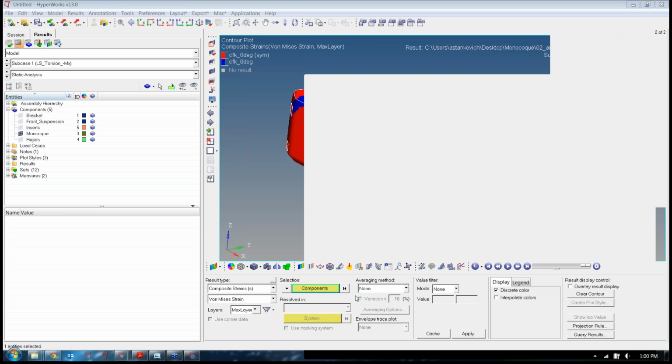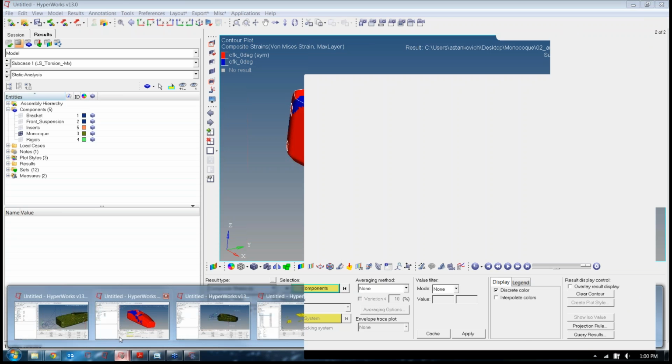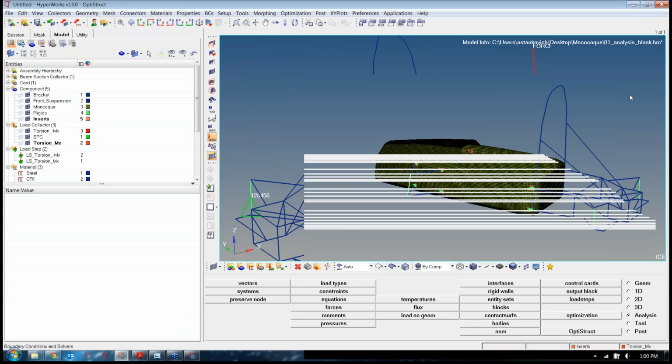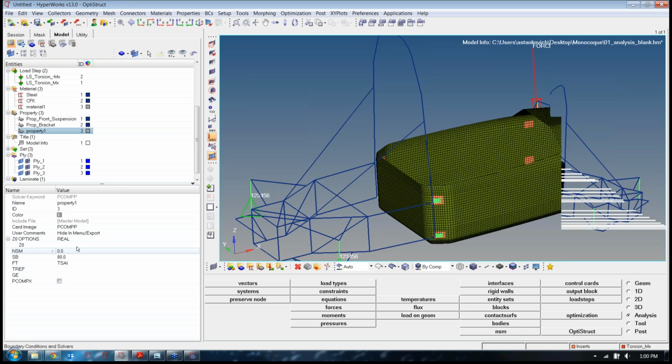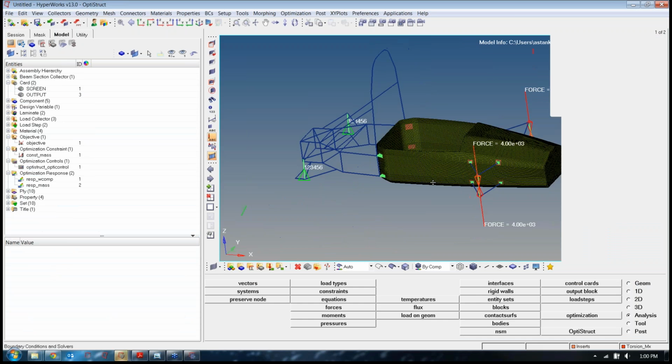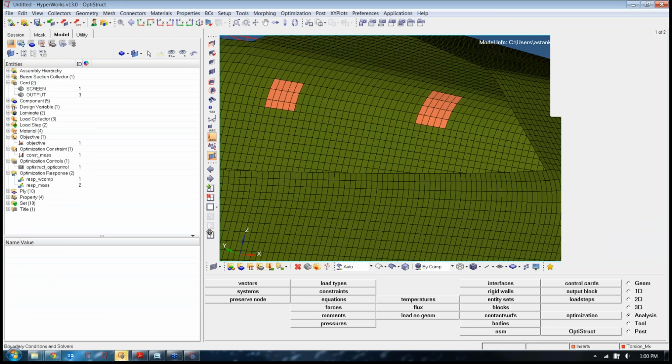So, is it possible to define an existing shell as a laminate inner or outer skin rather than being a laminate midplane? Yeah. So basically, I'll show you that option really quick, just because that's a very good question, especially if you have a specific requirement on the property card that I created. There's the offset option. Let me load one up really quick so you can see the plies.